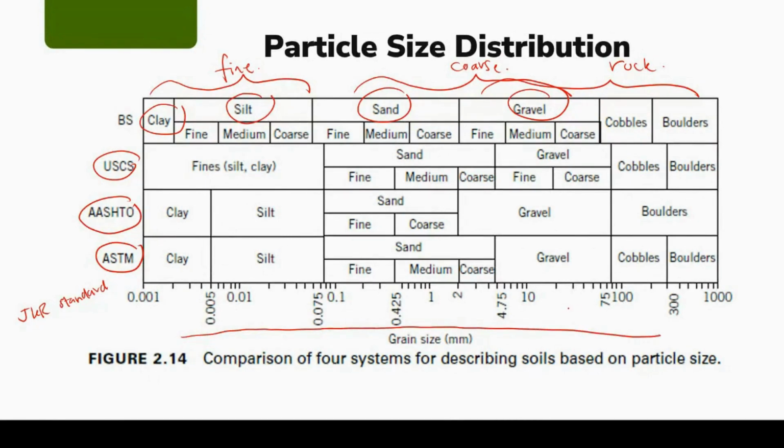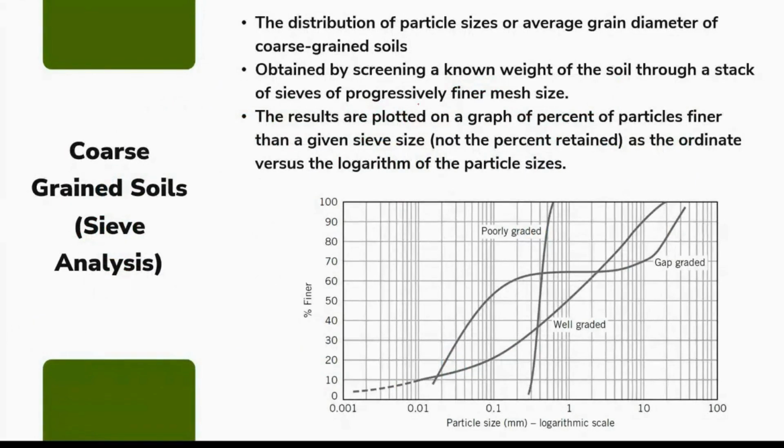So when you want to determine the particle size distribution, you may use the log graph. From the log graph you will get an S curve, so you can determine whether it is fine silt, medium silt, coarse and so on. Alright, if you can see here, there is the graph of particle size distribution curve.